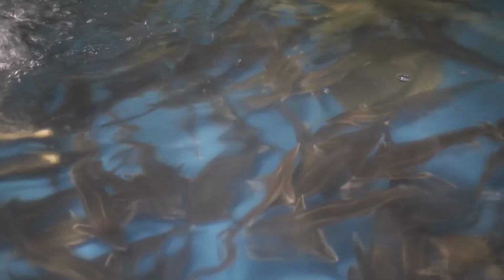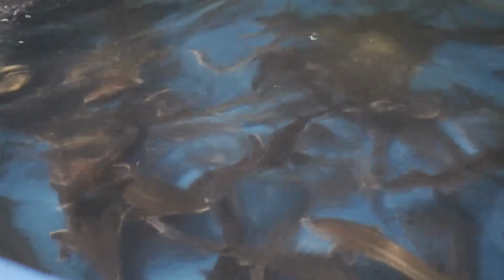But I'll tell you honestly, according to my experience, at a large number of operating RAS farms, the 40 microns mesh is used for fry, because fry fishes are small, and thus are better held by the mesh, and 60 microns for grow-out fish. Why? Because of a large amount of suspended solids. If you use a 40 microns mesh, it will soon get clogged, so you need a really big drum filter. And that's optimal for a sturgeon RAS farm with a temperature of 22-24 degrees Celsius inside.